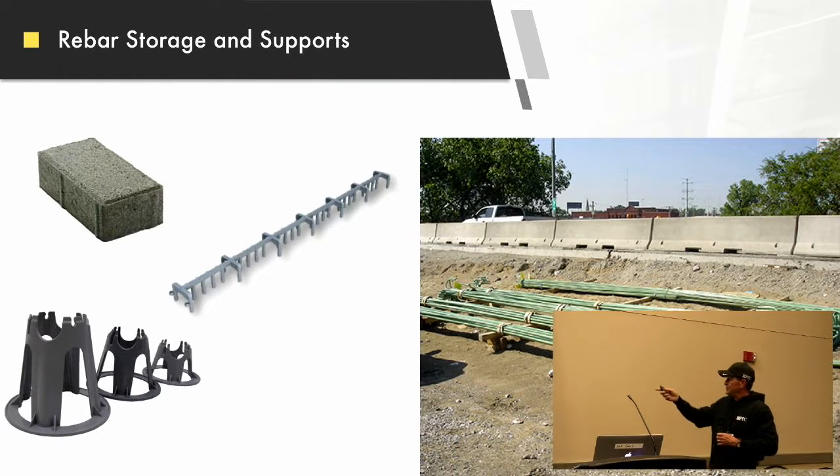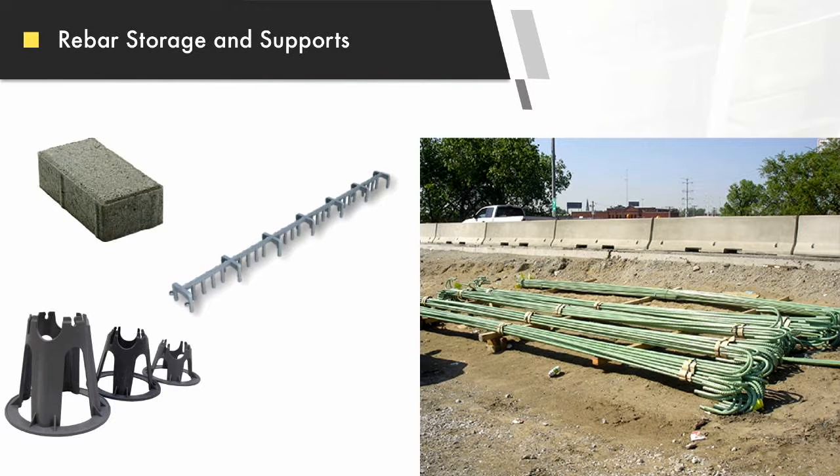This here is a picture of pretty good storage. They got it up on dunnage. Their tails are down here in the mud, which ain't good. But for the most part, they've done pretty good. They've got it up off the ground out of dirt. In the specification, it talks specifically about storage of rebar on site, and it talks about mud, dirt, all the elements that can cause damage to the rebar.